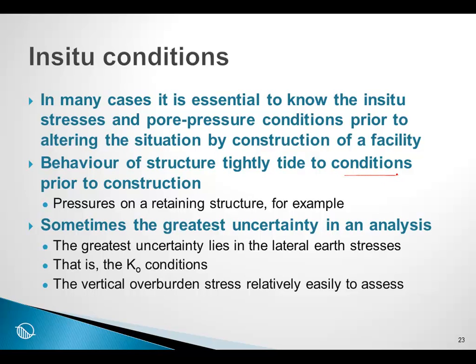in the case of a retaining wall, the pressure on the wall is very tightly tied to what were the horizontal stresses in the ground prior to making the excavation for the wall. And time and again, we will see that we need to start with a known stress state in the ground to do a certain type of analysis. But fundamentally also, the properties of the soil are related to the stress state. The soil stiffness, for example, Young's modulus, is a function of the stress state in the ground.